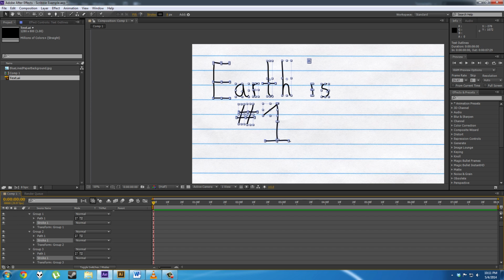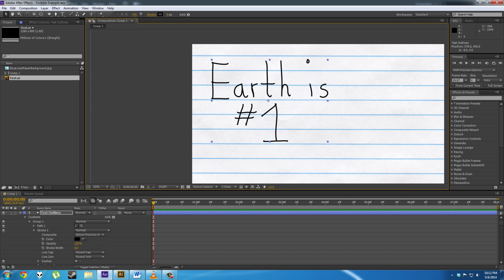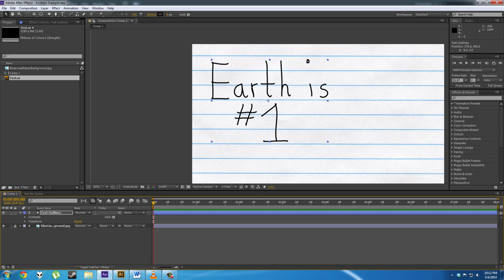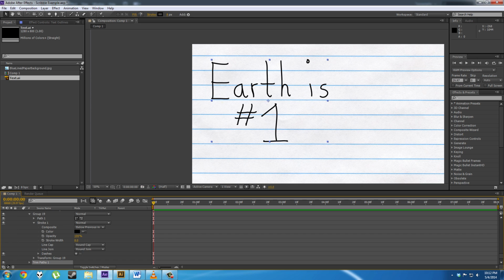So now that we have each of those selected, we'll drop down this, and then we'll select round and round for both of them, and it will apply them to all of the paths at once, and that saves us a lot of time. So now these are actually ready to be animated. So I'll go ahead and close the contents, and we'll go over to this Add dialog and click it, and we'll go to Trim Paths and add it.